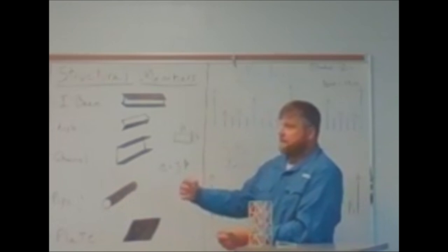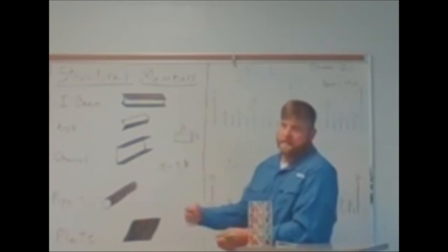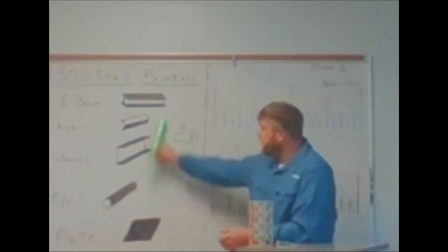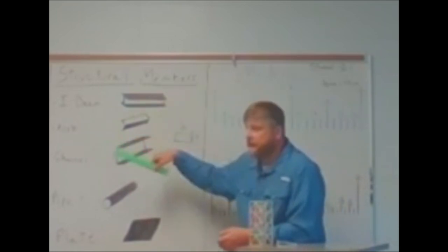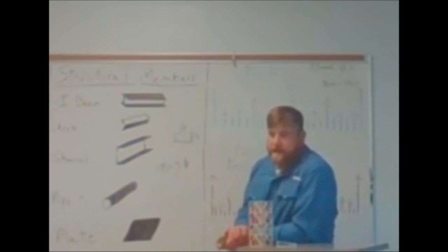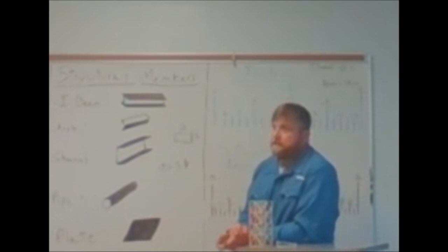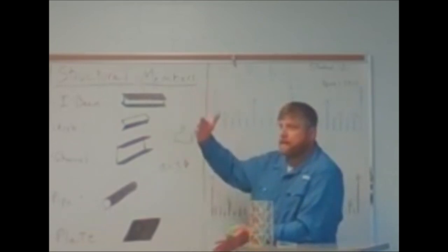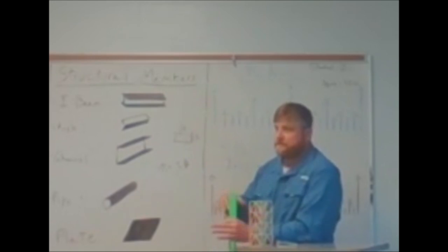So now, pipe has the same amount of material in 360 degrees around it. Right. So if you exert a force here, it'll be the same as exerting a force here, here, there. Pipe structurally could be a very useful component. Pipe is not used very often in structural design. I have seen pipe used structurally in places, primarily in things like hoppers where something has to flow past it, because it also doesn't have much resistance.